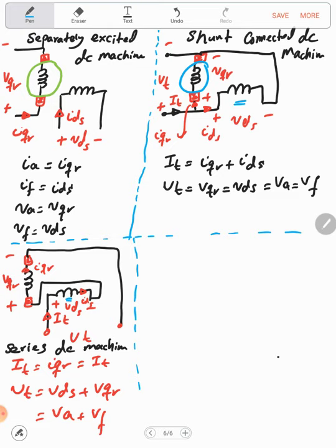Remember that sometimes the current in the armature will be very high. So simply, if the resistance of the coil will be high, this means that a huge losses will be dissipated across the field terminal, and this is not applicable. So simply in the series field windings,